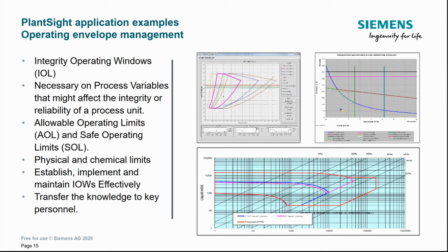from assets and processes, as well as simple target monitoring of the daily production targets, where some customers, for example, create KPIs in a very simple but very helpful way. I say, okay, let's have a look at the actual production rate. As long as we can fulfill our daily target with this actual production rate, the traffic light of the KPI is green. If we detect that with the actual production rate we cannot reach the daily target anymore, but we would be able to if we ran the maximum production rate, then it turns yellow.